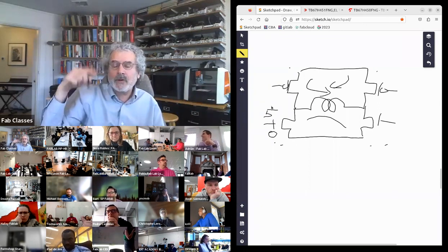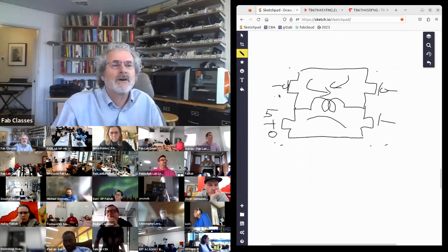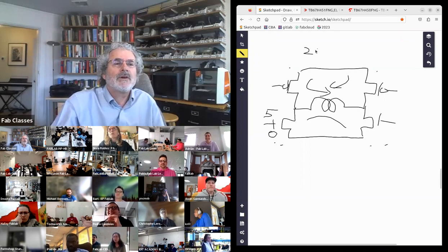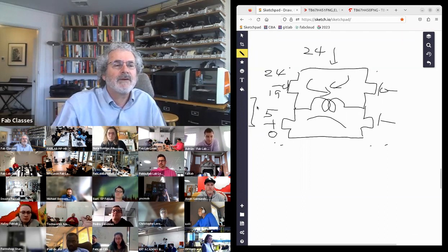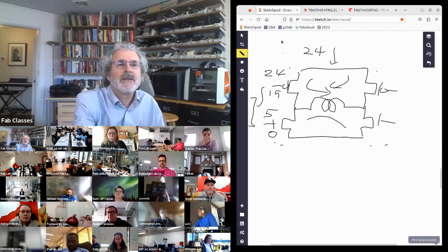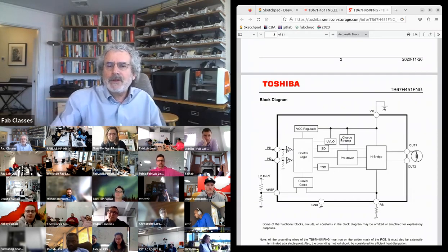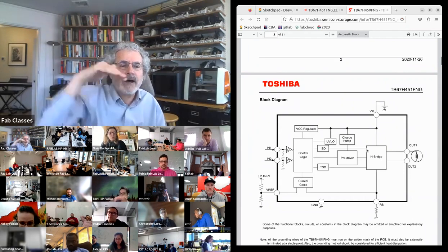For the MOSFET, it depends on the transistor, but we're using what are called logic level MOSFETs that turn on at a few volts, so say 5 volts. That goes from off to on. Here, though, the high side might be, say, 24 volts is how we're powering the motor. So on the high side, it goes between 24 volts and 19 volts to go from off to on. But our processor that's running our 3 or 5 volts can't make that high voltage. So the charge pump is a neat circuit that lets you put in a low voltage and it makes a high voltage. So we need the charge pump to control the high side of the circuit.